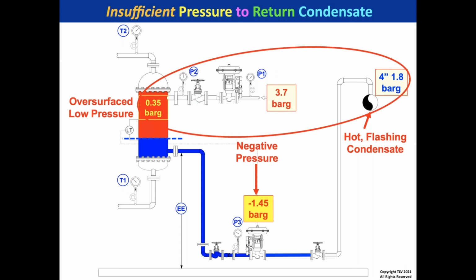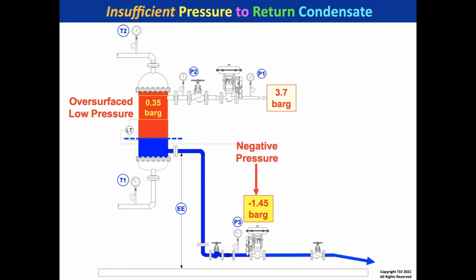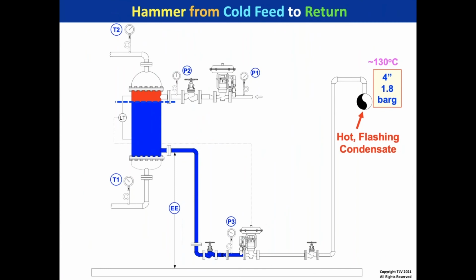And what do you think happened? So what happened was they dumped the condensate to grade for over 10 years. Well, somewhere in that time period, they said, well, let's just change the transmitter and let's flood more of the reboiler. So we just use very little of the surface area, the duty. And there you can see the pressures jumped up to 2.2 bar, which was great.